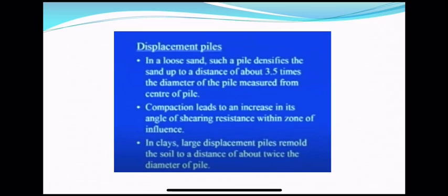This compaction leads to an increase in the angle of shearing resistance. So the zone of influence in this case is 3.5 times the diameter of the pile. Obviously, when the loose sand is compacted, the shear strength parameters increase.